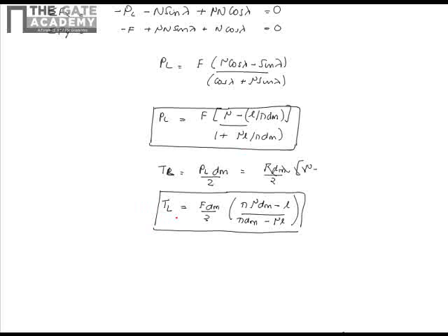When a positive torque is obtained from TL, that means we have to apply some extra torque to bring the load down, then the screw is said to be self-locking. The self-locking is a case where TL is positive.